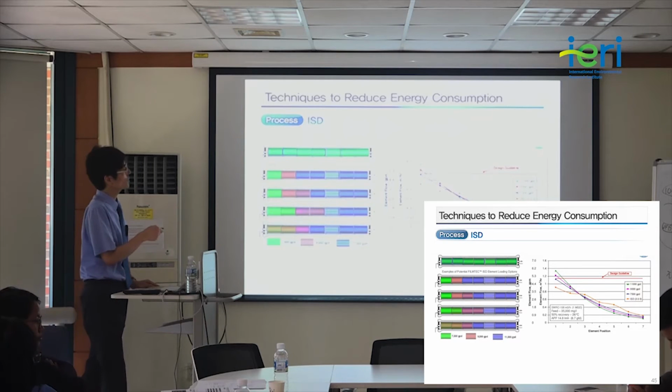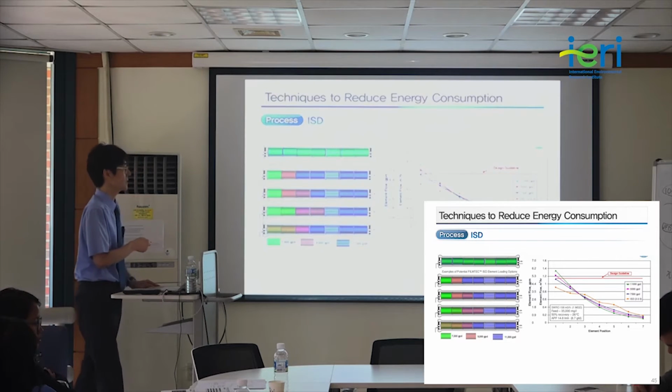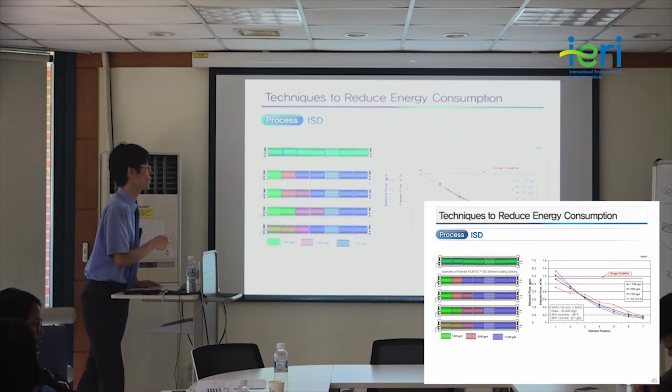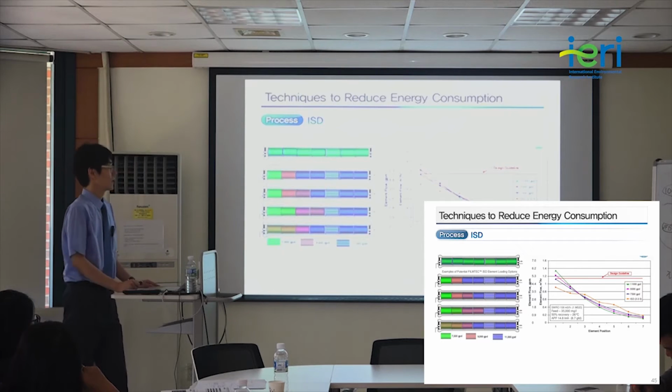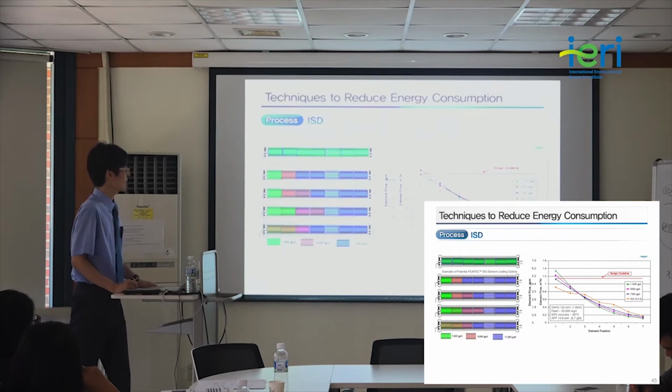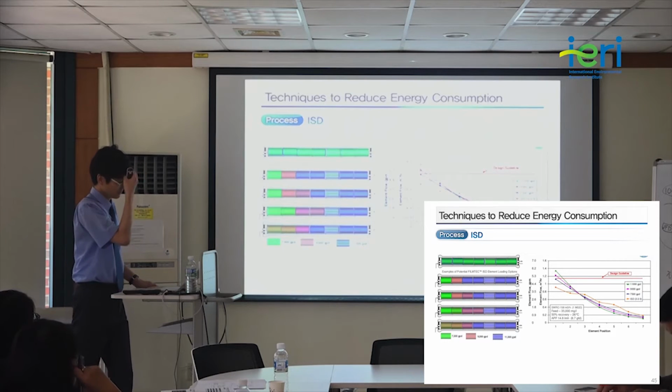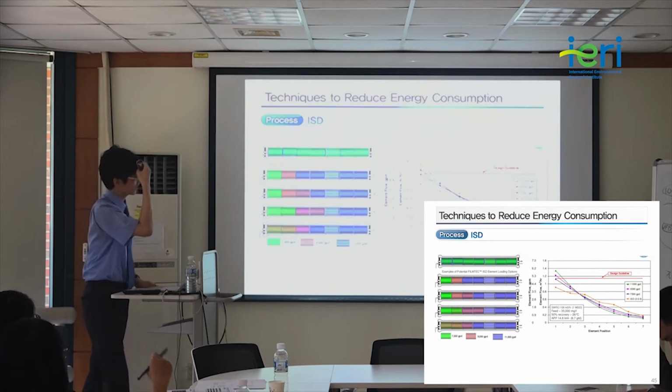But if you use membranes with different permeabilities, even if they have different driving force and different osmotic pressures, we can significantly reduce the variations in the product flow rate along this membrane vessel. I guess this concept is a little bit complicated, so I don't really know if you can fully understand what I'm talking about.